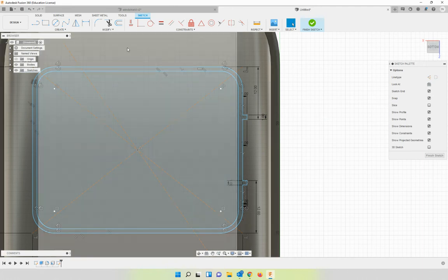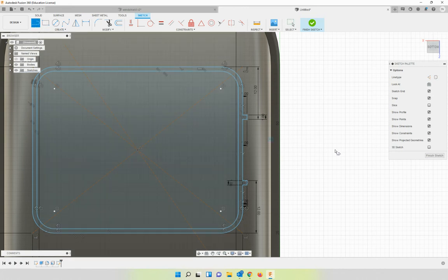I'm going to use the mirror tool. So let's go to the line tool, turn on construction. Let's come across our top line, find the center point. There it is, triangle, click, come down a little bit, click again, escape. I've now created a centered mirror line. Let's go create mirror. And we're going to select the 6 edges to our notches. All right, those are selected. I got 6 objects to mirror selected. I now need to change my selection to select the mirror line. There's my mirror line.